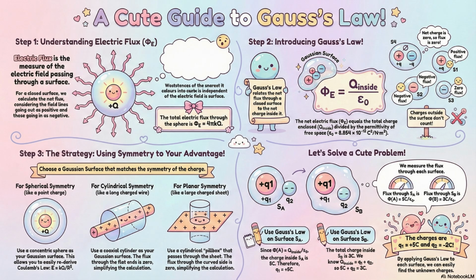So we established that a capacitor stores energy in an electric field. That means its capacitance, its storage capacity C, must be directly proportional to that dielectric constant epsilon r of the insulator between its plates. Exactly. The better the material is at containing the field, the higher its epsilon r, the more capacitance you get for the same physical size. Now here's a point of confusion I want to clear up for you.